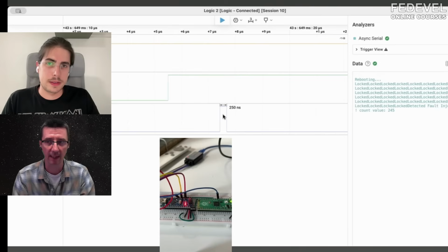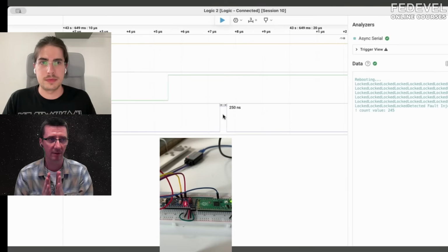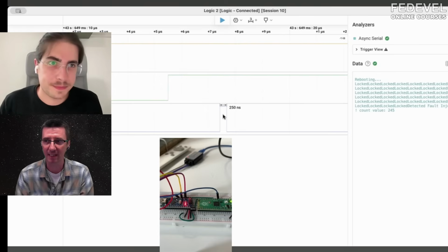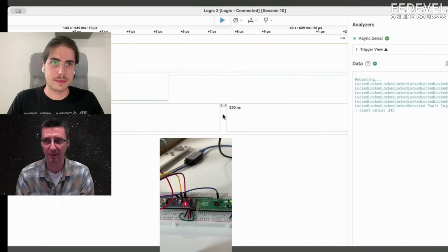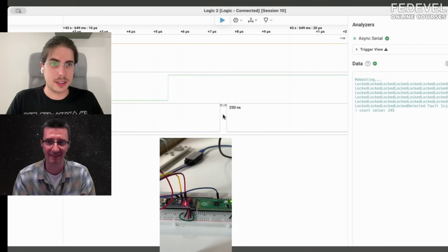But what is also interesting is that if the pulse is too short, then the board will not crash. Only the one instruction can be affected. That's what you want to achieve. I would expect that if the voltage drops, the chip resets or something. No, it doesn't reset. It continues, if it's only a very short time, because you have capacitance, you have charge.